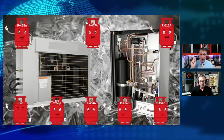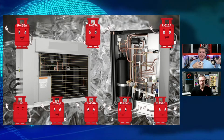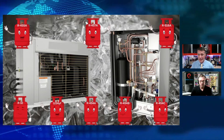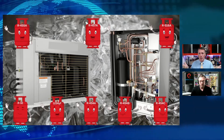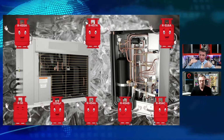If we take that R32 and we want to reduce the global warming potential of it, we just blend it with some 1234YF. And in different blends, different concentrations, we get R454A, B, and C, right? So they will work with different refrigeration applications, different coil temperatures, really what it comes down to, and system performance. So we're going to have different blends in there.